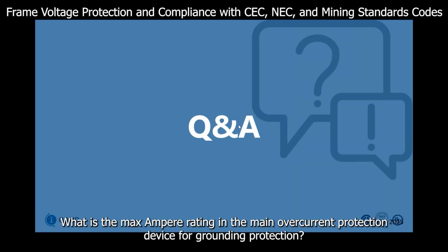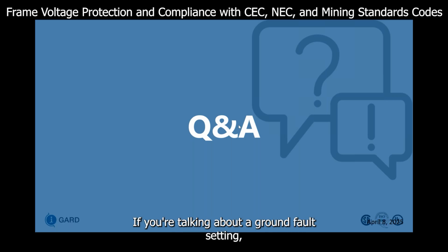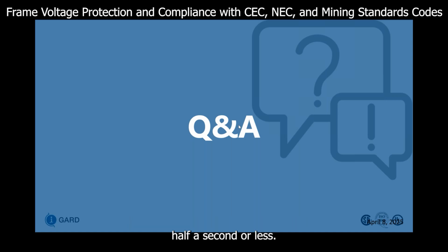What is the max ampere rating of the main overcurrent protection device for grounding protection? If you're talking about a ground fault setting, usually for mines they use a 20% pickup and are tripping within half a second or less. Thank you for the good presentation.